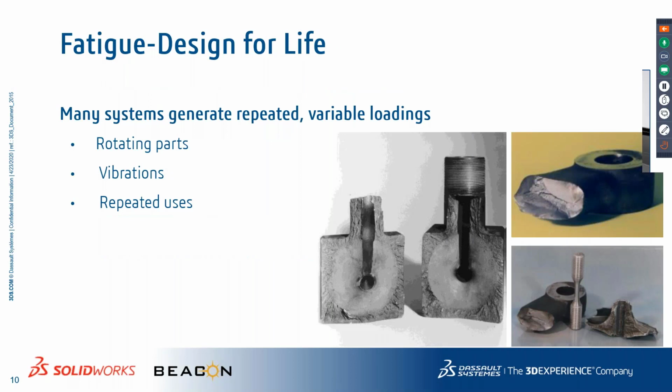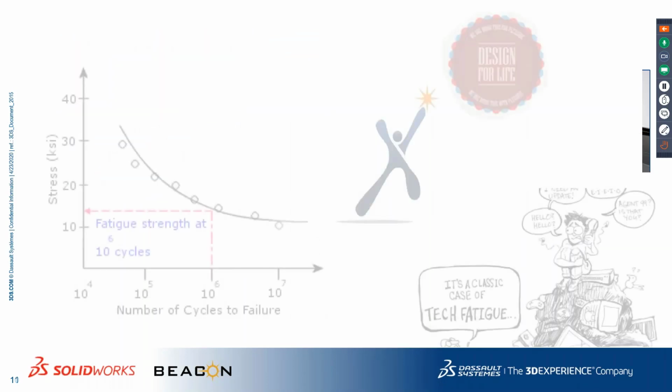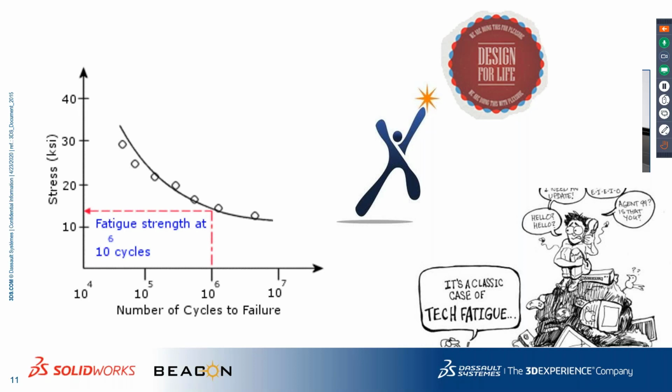Moving forward, when we see these particular machines, all these structures will experience repetitively applied loads, because only strength analysis is not sufficient to decide upon the life of this product. A lot of vibrations will be generated, and there are a lot of rotating components, which apply loads repetitively. For that, it is also important to consider fatigue analysis, because so many applied loads are repetitive.